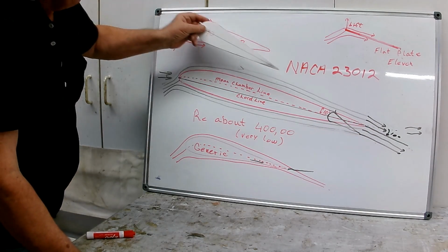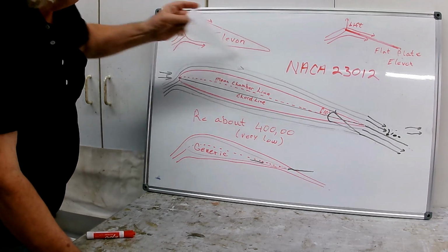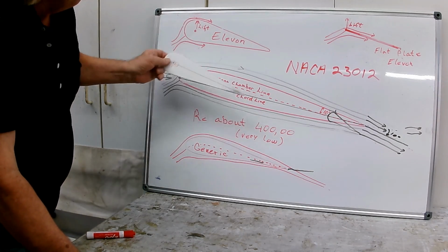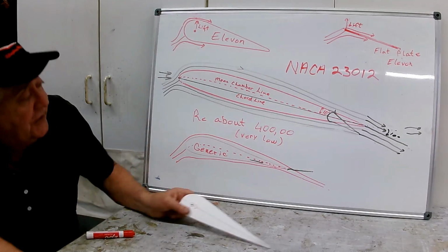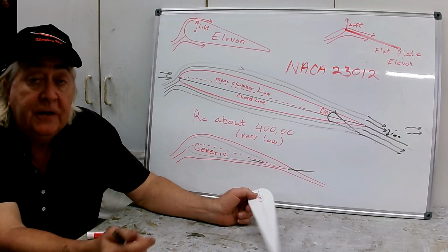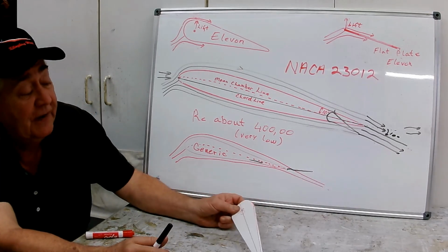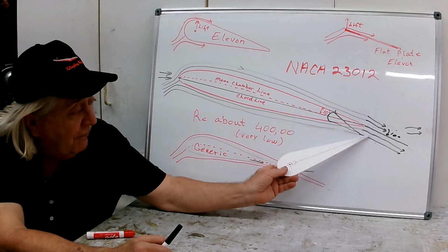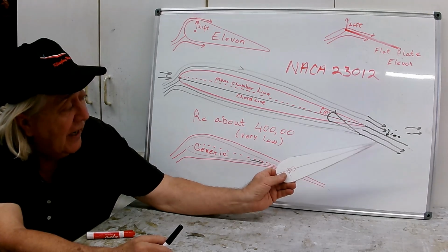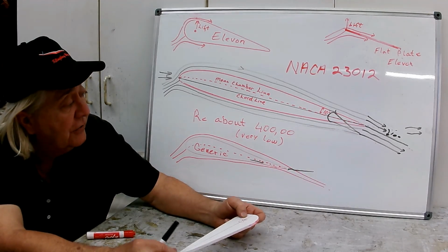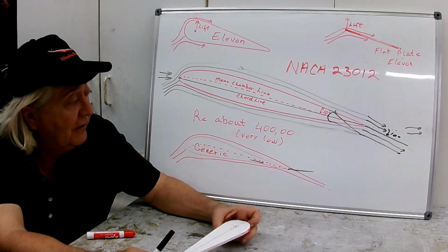So it's not so much the lift that we generate on the Elevon, which is what the case was here. Of course, this guy does double duty. When you deflect him, you get lift off of this surface, but you also change the lift of the airfoil. And when you change the lift of the airfoil, you get much more rolling moment. So that's another reason why these are a little less effective. However, this avoids the problem of creating that discontinuity there, and you can get 10 degrees of deflection to do control of the aircraft before you start to have a discontinuity show up.